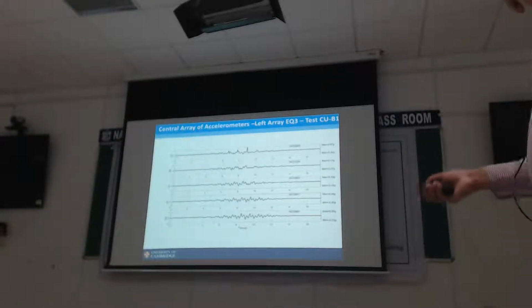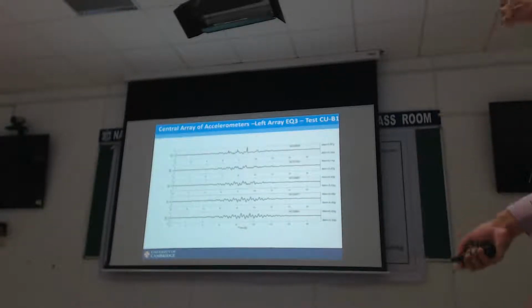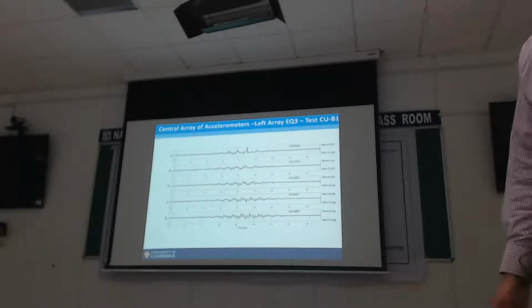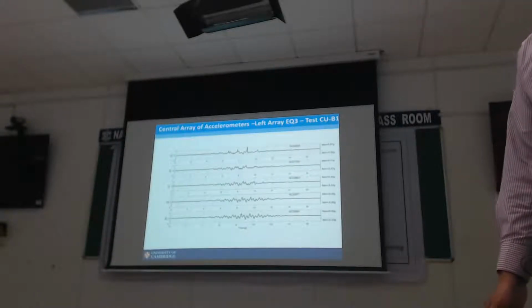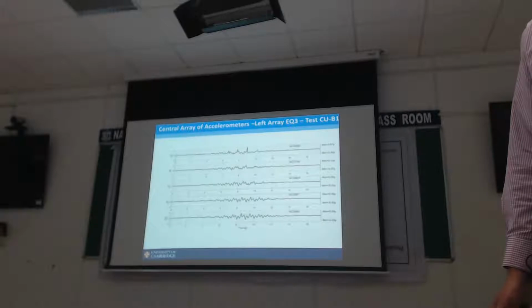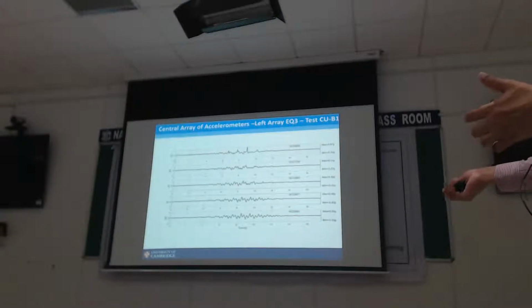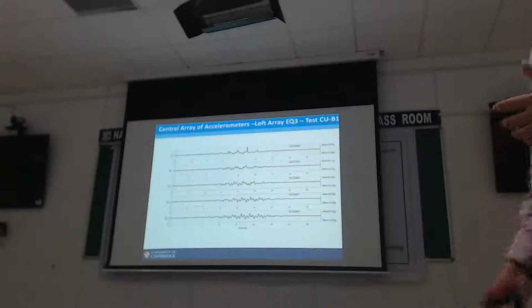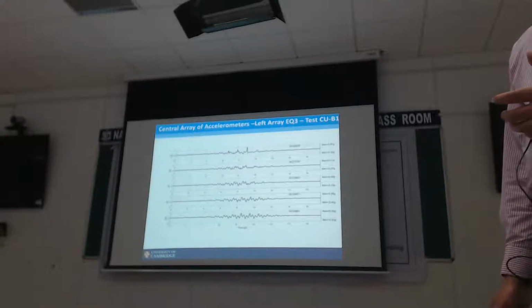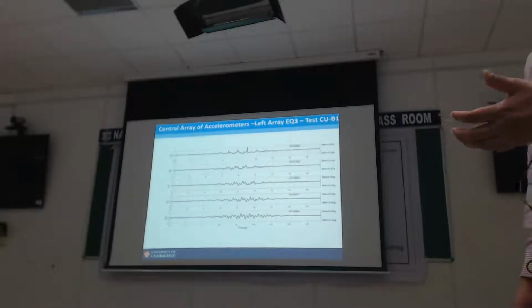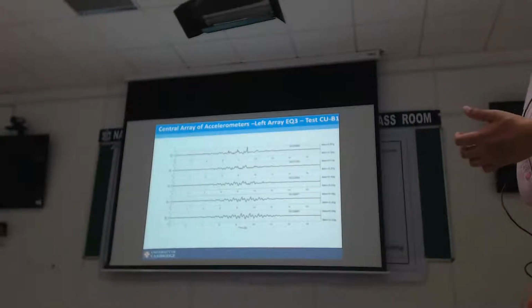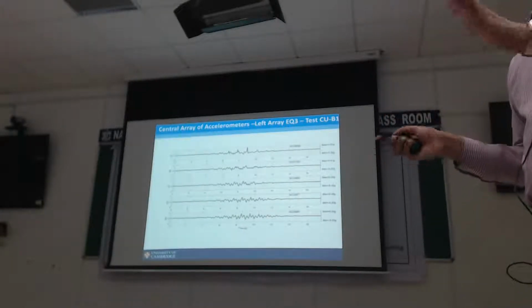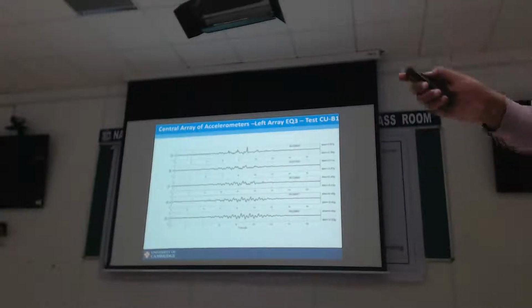In theory, this number, because I'm using the same scaling laws, should be the same for this slope as the other one. But in the other case, we put 0.27, we got 0.38. This one we put 0.5, and we're getting nearly 1. And if I put 0.25, nothing happens. So the slope does not move. Clearly, you're starting to see the differences between the 2 models.